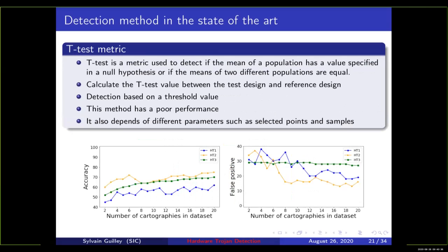Okay, so what we will be doing is to repeat the measurements. We will be scanning the FPGA surface not only once, but n times, in this case 20 times. And as we grow the number of traces, so our matrix, the size of our data, the campaign, we check how we manage to improve the accuracy of detection and the false positives.